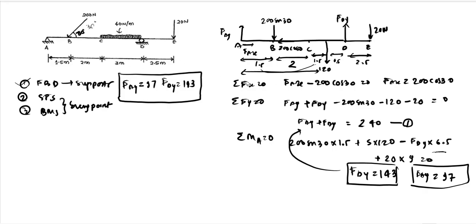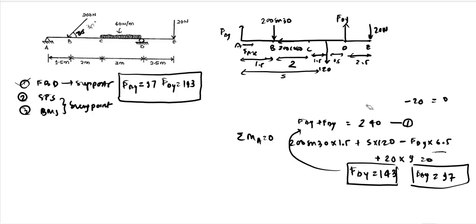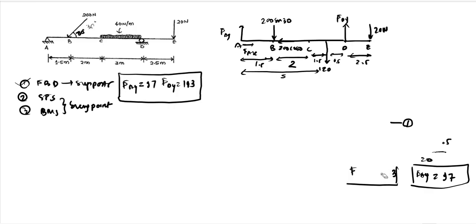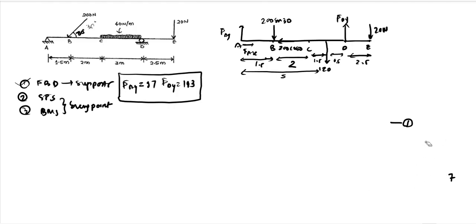So yeah, let us just move on to step 2, which was calculating the shear forces at every point. This should be 5 as the total distance. So let us calculate the shear forces at every point to make the shear force diagram. For step 2, starting at point A, the shear force will be the reaction at point A, which is 97.